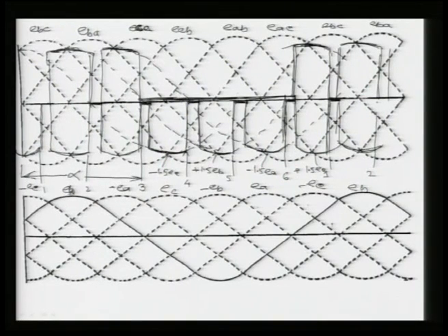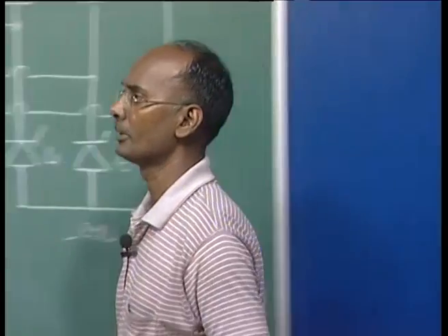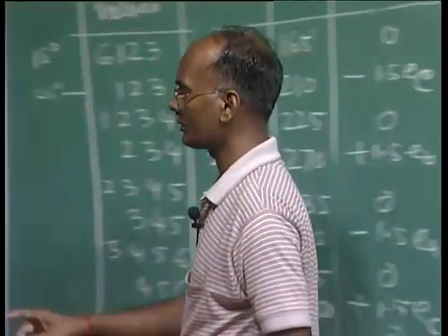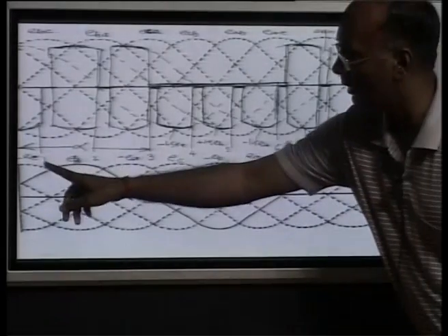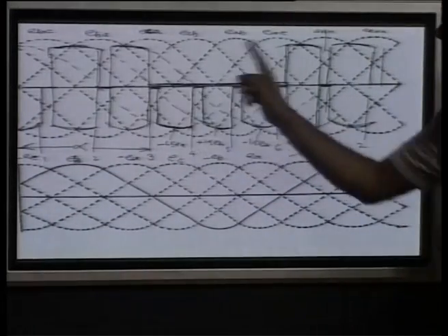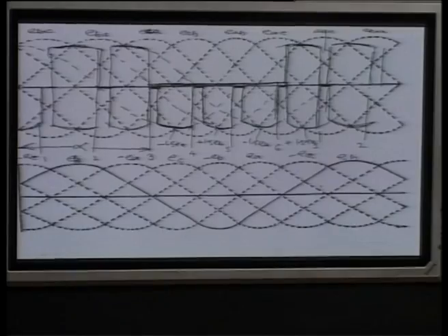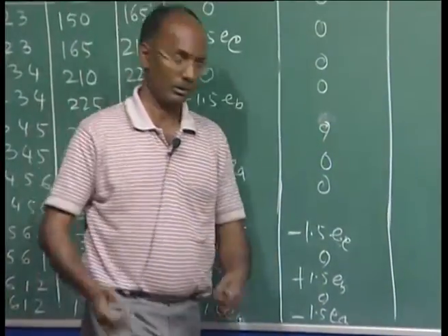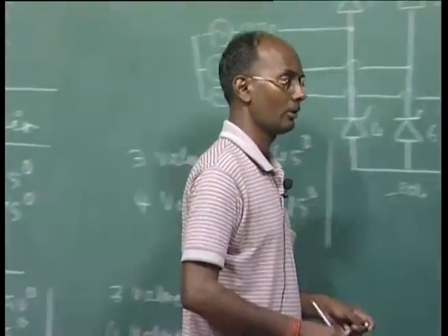So, you can say 1 is starting here, means 3 output pulses we are getting in this cycle. In the complete cycle, here again just 1 is coming, means we have reached here, and then we are having 3, and already here you can see the output voltages are 3 times there, and the remaining time it is all the way 0. So, this is the valve voltage which is appearing across the valve 3. Similarly, you can draw for the others as well.